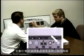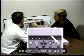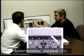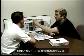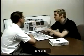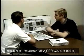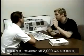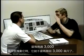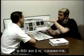Pulling it is asking for a selected vertical speed or flight path angle and track flight path angle. If I pull that, it's going to come up into whatever my current vertical speed is, and then I'm going to dial it around. Okay? If I push it, it's asking for a vertical speed of 0. That doesn't mean the airplane's going to level off at the altitude I pushed it at. It means it's going to decrease its vertical speed to 0. So if I'm doing 2,000 feet a minute in a climb, as I pass 3,000 feet and I push it, it's not going to come back down to 3,000 feet. It's just going to level off wherever it achieves 0 VSI.